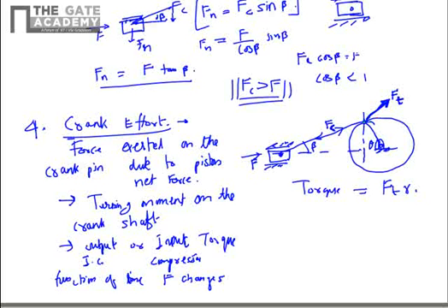To see how the transmission takes place, you have to draw the balance of forces along the component in this direction. For that we extrapolate this triangle and draw a perpendicular from the crank center to this triangle.